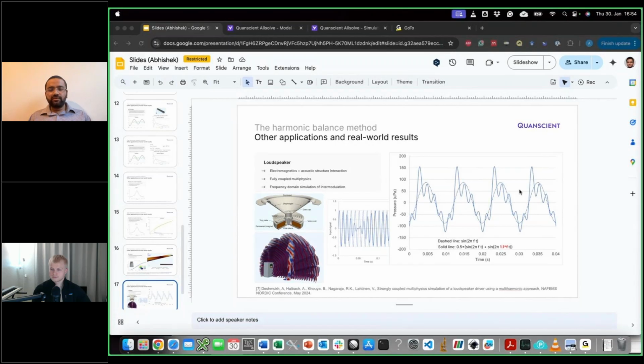One typical case where the harmonic balance method would not be useful is the impulse response, because there is a step response that you have to provide, and to capture the step response, you will need practically a quite large number of harmonics, and that's where the limitations of this method come in. So in those cases, it would be practical to use transient simulation, purely because of the computational demands.